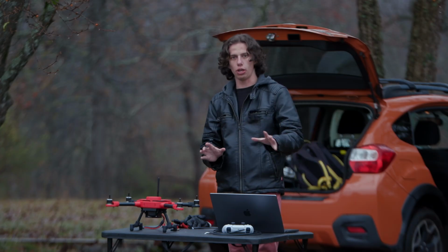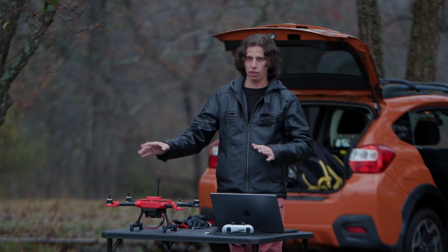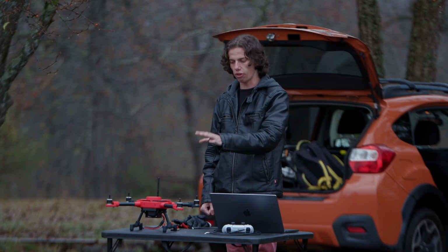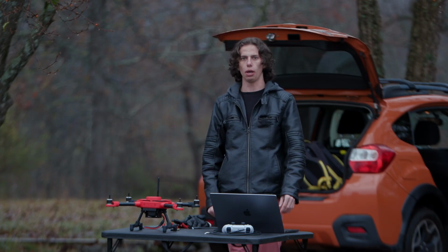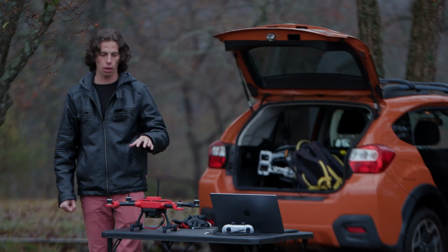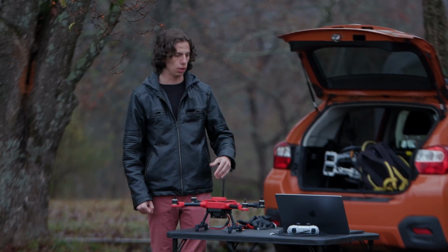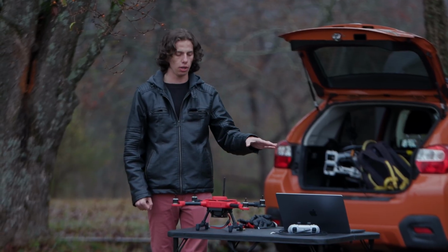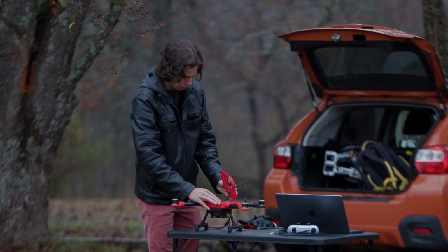While you really shouldn't ever have to use QGroundControl or Mission Planner, hopefully, from this point moving forward to fly Develop Air, we really don't have all the configuration or setup options that you need, like to do a compass calibration or accelerometer calibration, to do motor testing, any of that built out in the iVue RC app. So while you can use Mission Planner, I personally prefer to use QGroundControl for most of this setup and configuration.